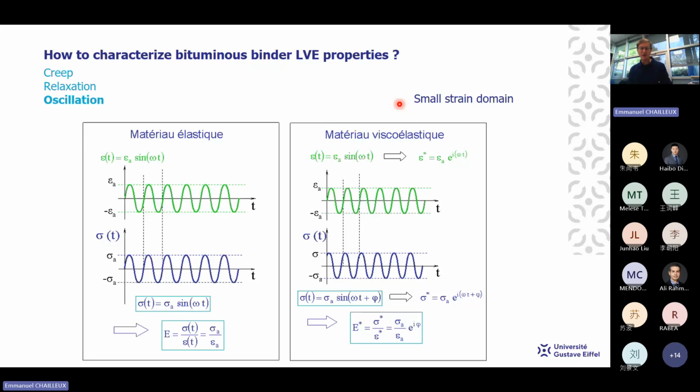It's a way to verify that you are in the linear domain. So in the case of an elastic material, the sinusoidal response is in phase with the sinusoidal input. So you don't have a phase lag.